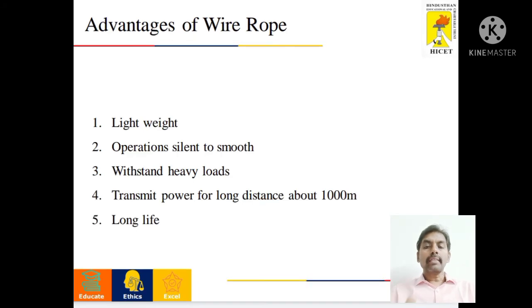Next, the advantages of wire ropes. One is that it is lightweight. Second, the operation is very smooth. Third, it withstands heavy loads. Fourth, it can transmit power over a long distance, about 1000 meters. And the last one is a long life. The life is very long compared to chain drives and belt drives.